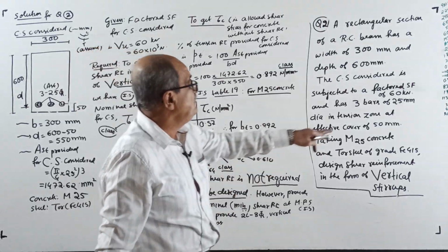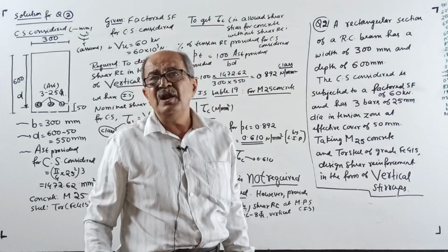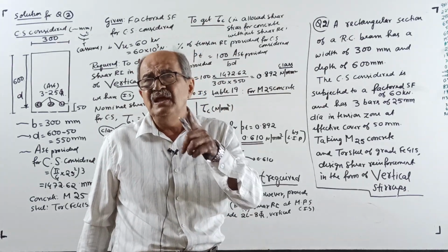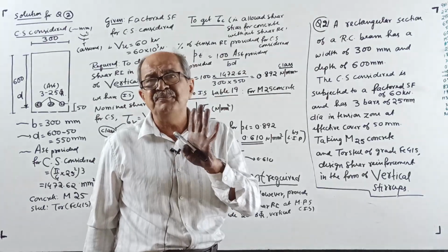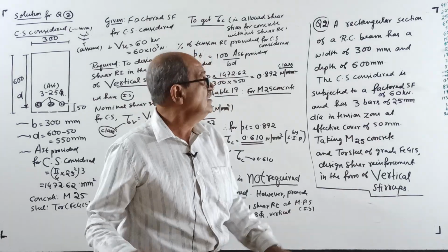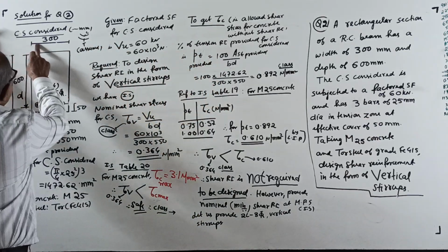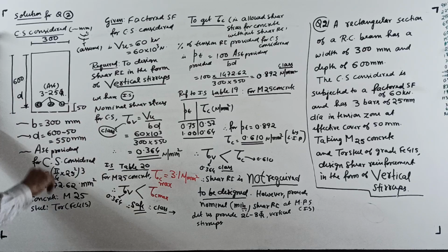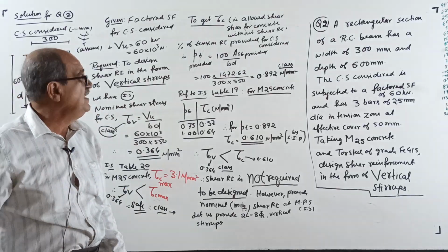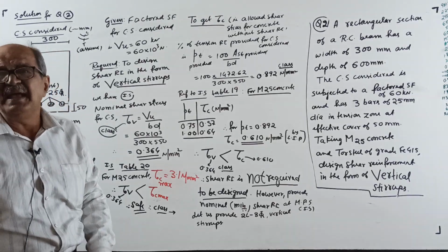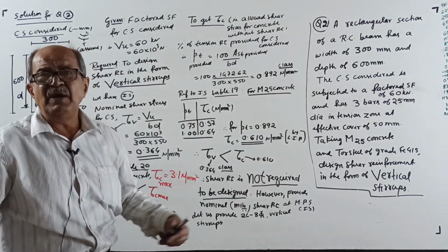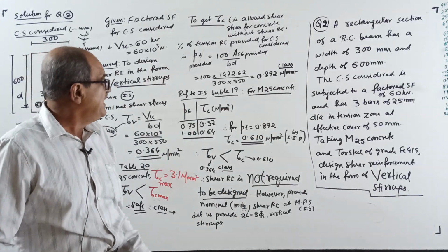Make a note. If simply shear force is given, or if it is given as per service load or working load, without forgetting, you have to multiply by gamma f, 1.5 under normal cases, and get the factored value. Over. Start. Cross section 300 by 600. One more thing. In the successive change of problem, sometimes by mistake, human nature, some numbers might have slightly interchanged. I am careful.